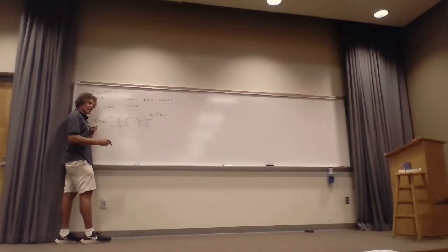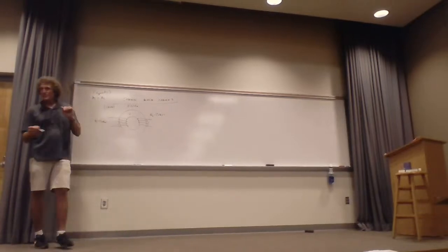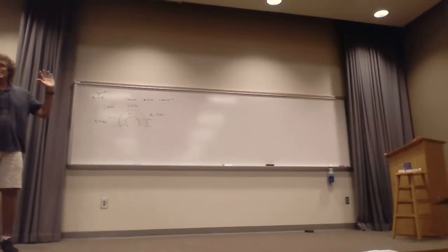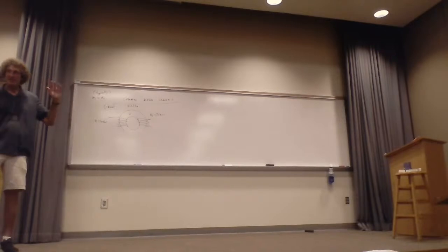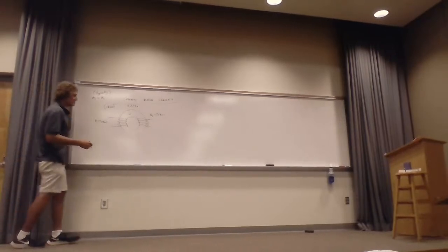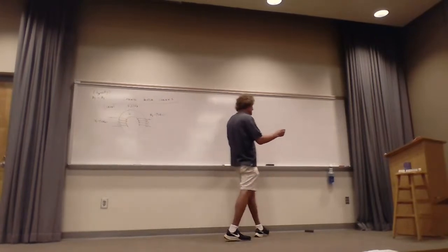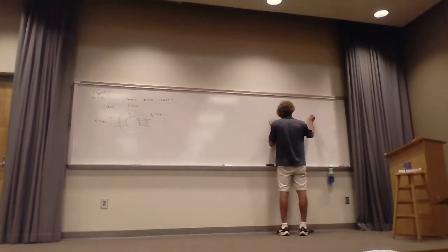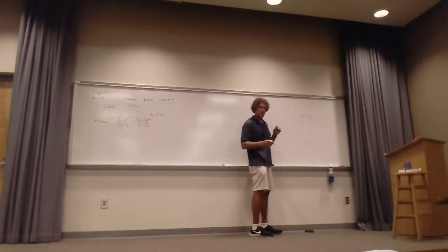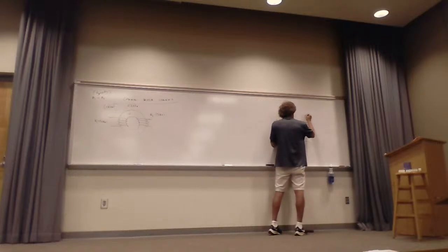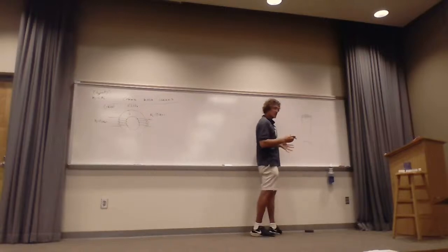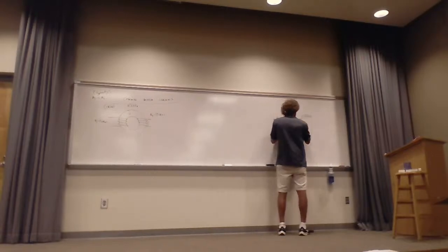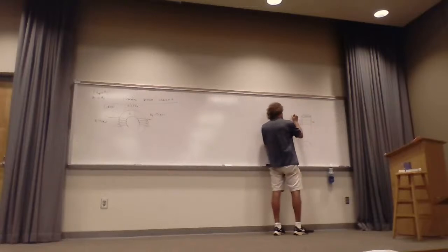If you look at this, and how many have had Gross here for power? Gross does this. He does it with the flux linkage. He does this kind of stuff. Let me step over here for a second, make sure everybody understands when I talk about inductance in general, how to get it. If you just had an infinitely long straight rod, it's going to be a ferrite rod, so the mu here is large. In this material, just a rod. And I wrap a set of turns, call it N1 here, and I put a current I1 here.